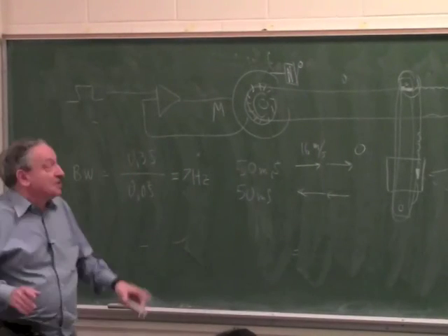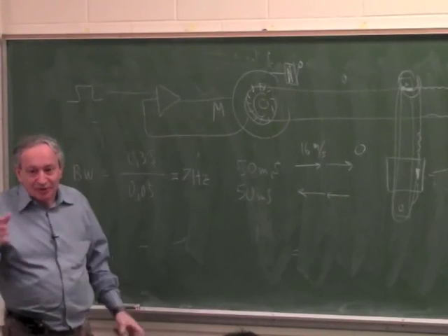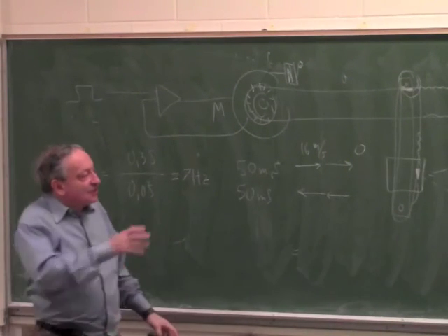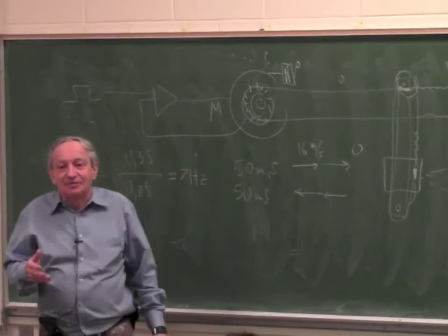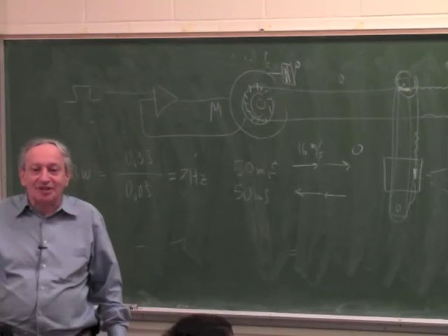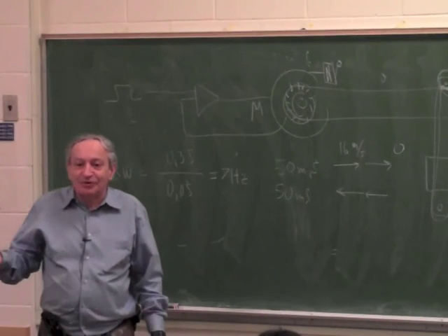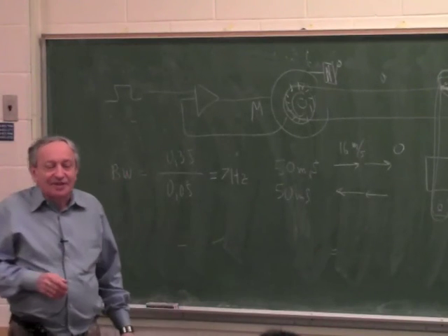So this whole process, this is the steps you take in a servo system design. This is not how to do the servo itself. Of course, you have to write code for the servo. That's a different problem. This is just, if you're given a spec, how do you convert it to parameters you look up in a data sheet? How do you convert it to bandwidth? How do you convert it to power, to force, to accuracy? Is that clear?